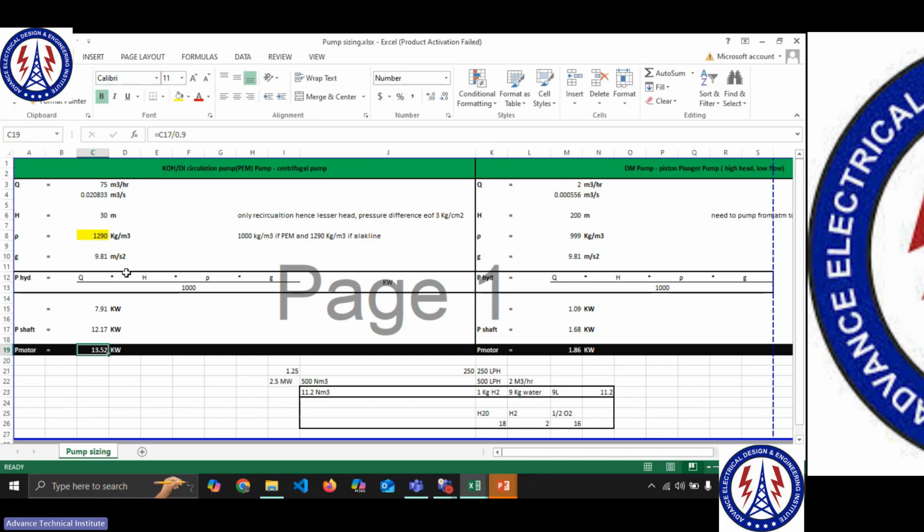We are not going to detailed design. If you go to detailed design, then based on motors, RPM, and how much flow there will be, all of that the vendor will provide. We don't need to go into those details because we are just concerned with the basic design. We need to arrive at a number which is very close. If you actually go into pump sizing, then you will get a flow RPM curve, and at what power what flow will be there. It will be like a pump characteristic, and based on that you will buy. For a preliminary calculation, this should be good enough. This is the fundamental, first principle based calculation.